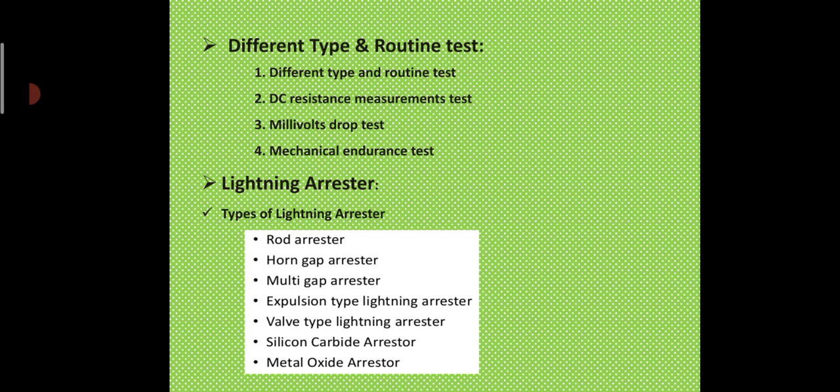For spring, hydraulic, pneumatic mechanism operated, the shunt release should operate at 85% and 110% of rated supply voltage. The oscillograph records are generally obtained on multi-channel ultraviolet recorder. The DC resistance measurement test is a very simple test. The resistance of main circuit of each pole is very small, a few micro ohm. The resistance is directly measured by a sensitive micro ohm meter.